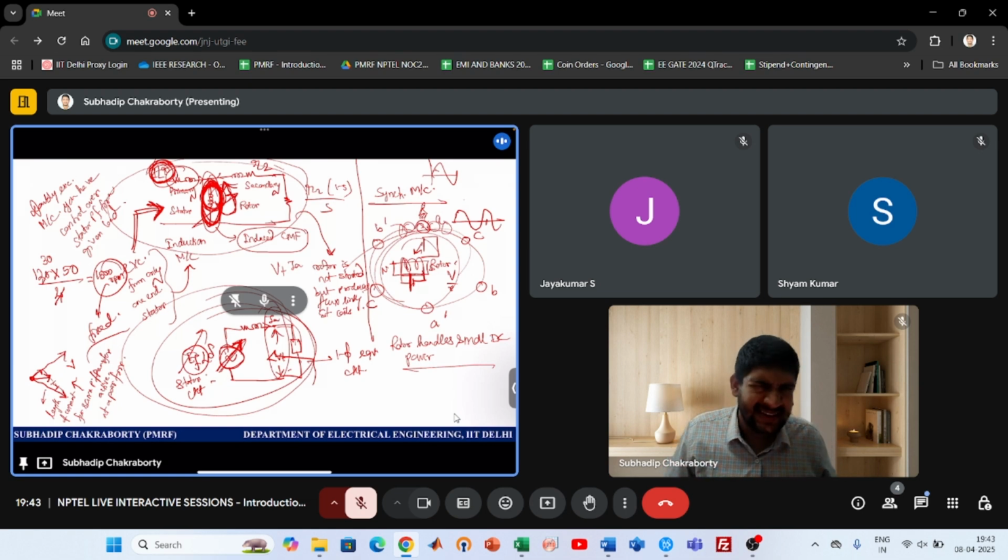You are getting the mechanical effects only due to the active power, because reactive power over a cycle comes and goes. So it only results in copper losses, because the current component comes and goes and results in I RMS square R losses in the line, but doesn't result in active power transfer from source to load, because it never goes from source to load. Only active power generated by a system helps in the power transfer.